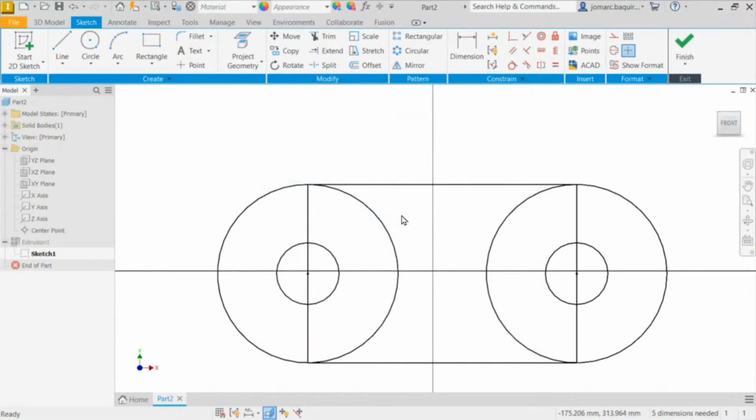The difference with Inventor is we can do that right away. Actually, that 0, 0, 0, the XYZ 0 coordinates, is hidden by default, and it's actually this center point. So notice that yellow dot, that's actually the center point.